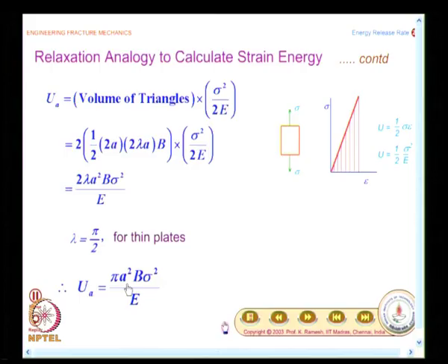So, when the crack length changes, the energy would change as a parabola, second degree curve. And now, we will look at for the formation of two new surfaces, what way we require the energy. If you look at these two natures, we can understand there could be a crack growth phase and a catastrophic crack propagation. We would try to plot them.